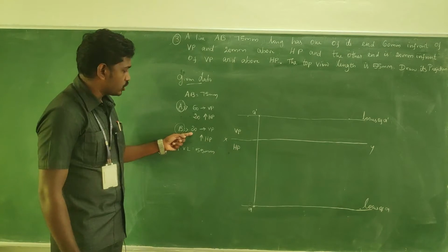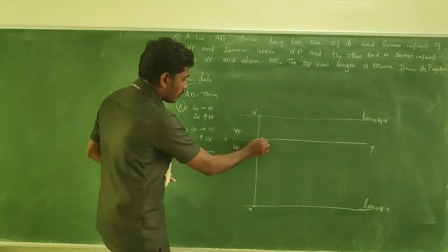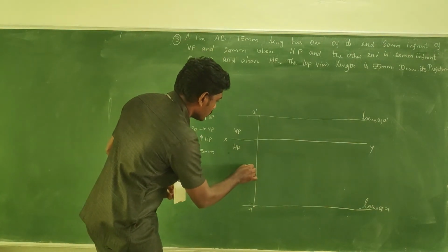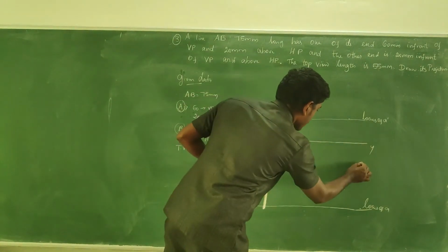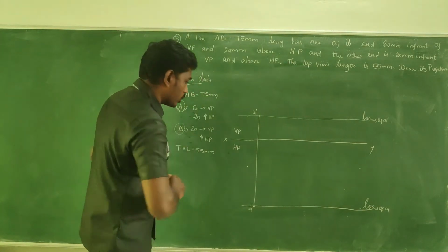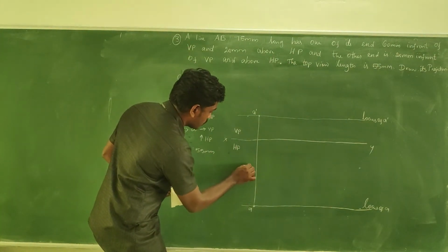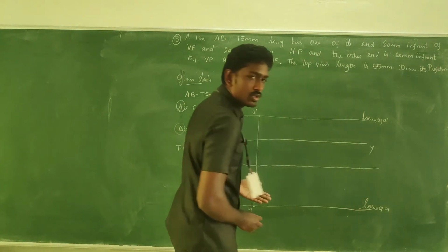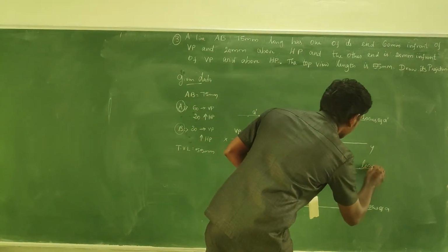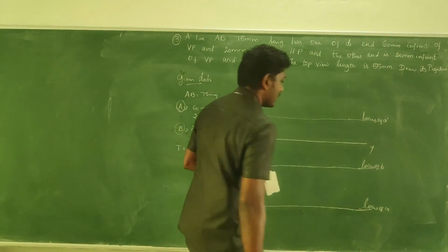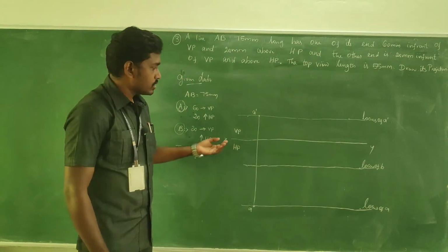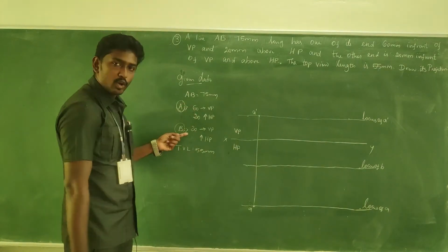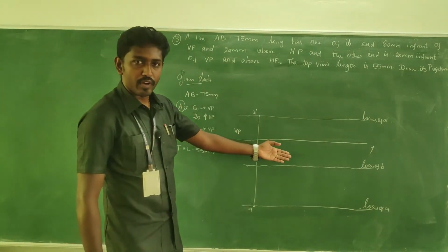Okay, what is next? We have to follow to the next locus, B. What about B? It is 20 mm in front of VP. So from the reference line measure 20 mm, measure it on both sides and join both points, something like this. So this becomes the locus of B, the other end B. Okay, so all the 3 loci have been taken to the profile.